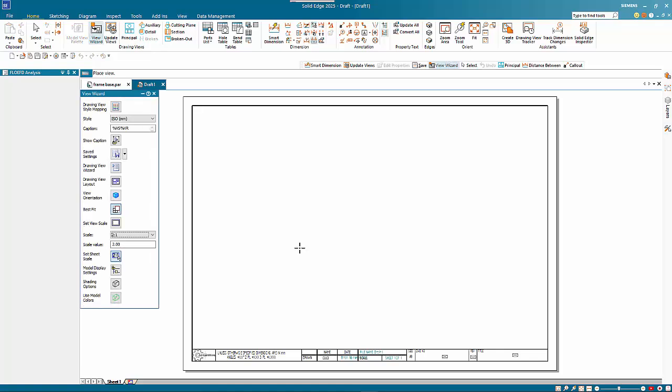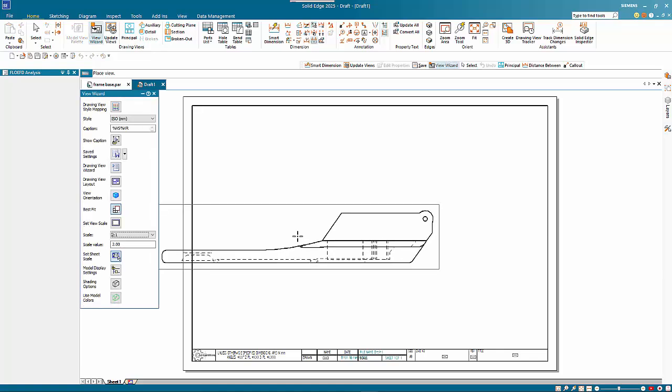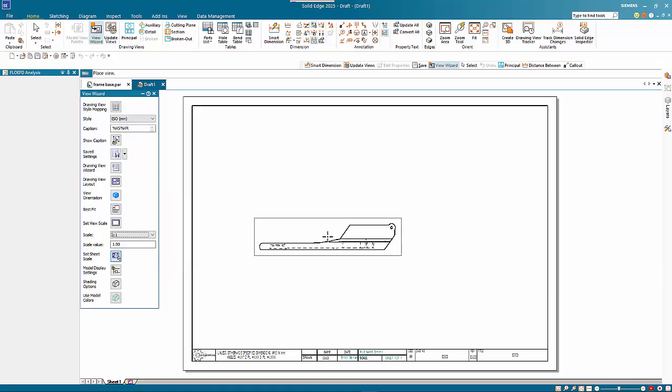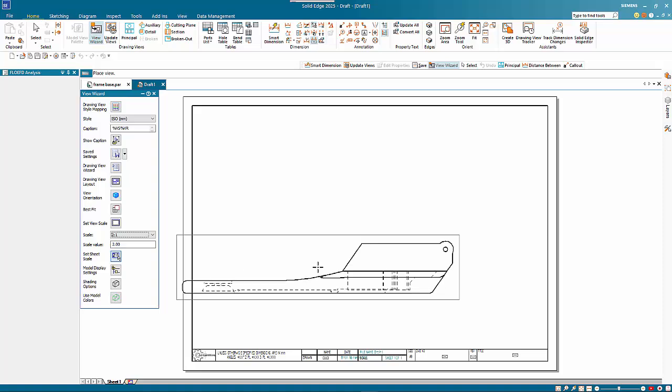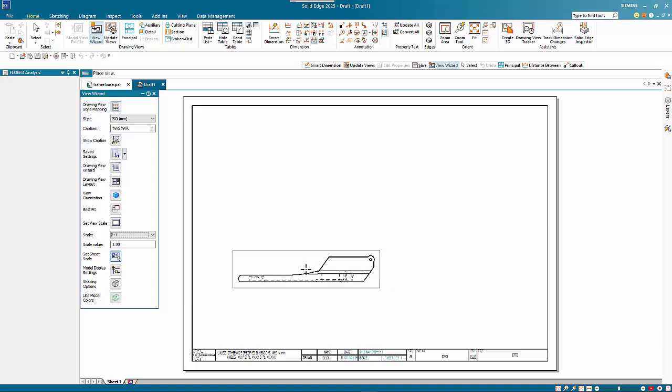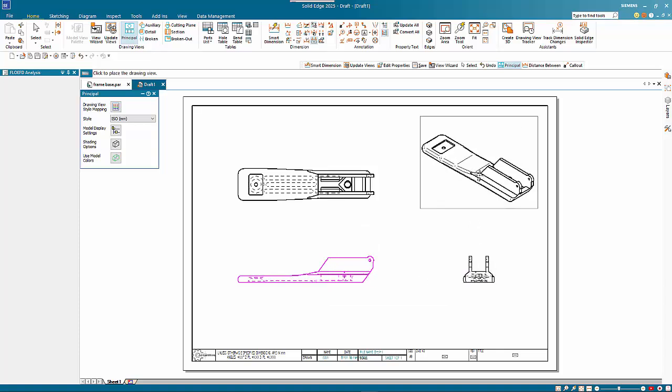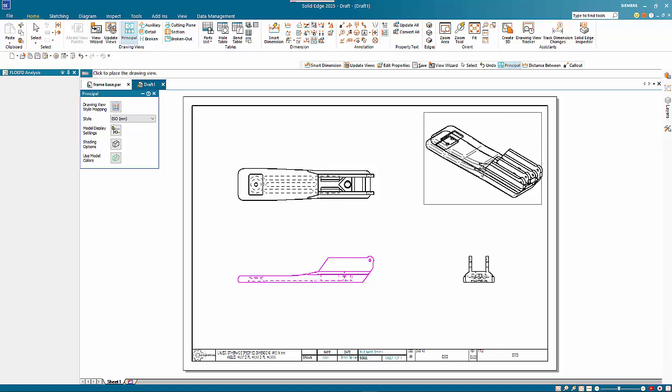And we set it up so that it runs the drawing view wizard. You can see here we can use the scroll wheel to zoom in and out to set the size that we're after. And I'm just going to break here. I could go in and add in extra views, and maybe I will do that so we can drag those off. This is third angle projection.